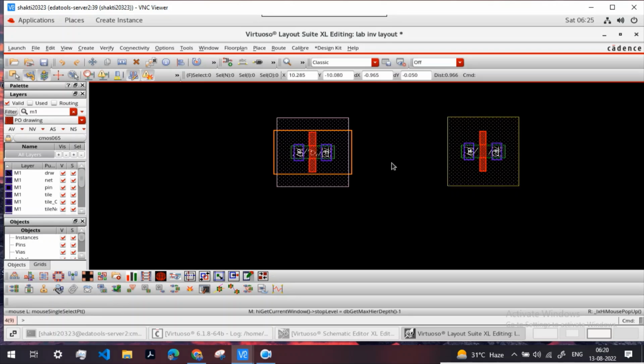So for making the PMOS inside the P-type substrate, we first need to create an N-well, which is a region of N-type substrate, and then there we dope P plus source and drain to create a PMOS. So for NMOS, I don't need any P-well as such because the whole black region is itself P-type substrate.